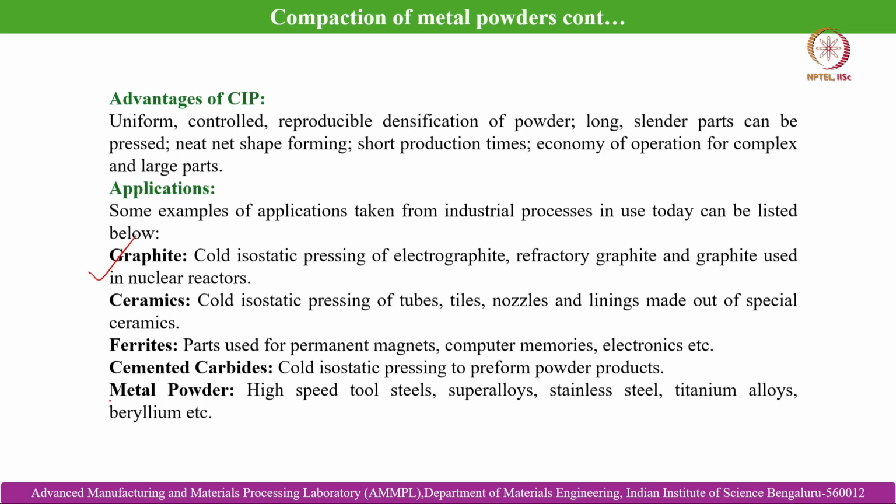In this case, try to understand, we are not talking about net shape parts. Rather, we are talking about developing special purpose alloy specimens, which are otherwise difficult to develop by other routes, like melting and casting routes. So, they can be effectively manufactured by the PM route, for example cold isostatic pressing, where we develop the preform or sample, and then do post finishing operations such as machining and heat treatment, etc., to achieve the desired set of properties in the sintered part.